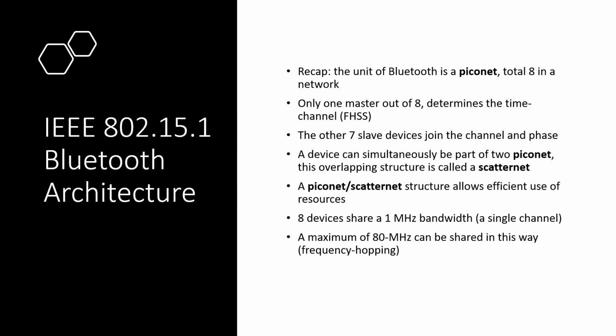I think you have already learned this, but I'm still going to give a brief description of how FHSS works. It usually uses a broader range of frequency channels and randomly selects one channel to communicate. After a message is sent, or after a set period of time, it quickly changes the channel to a new one. It keeps changing the channel after a specific period of time, so that it cannot be understood which channel is currently being used.